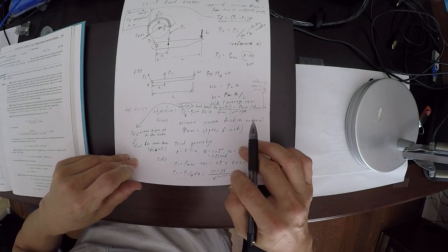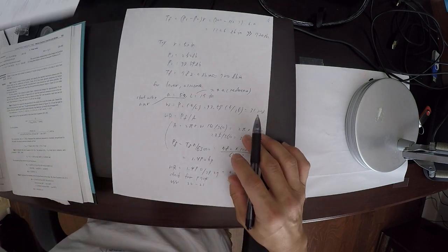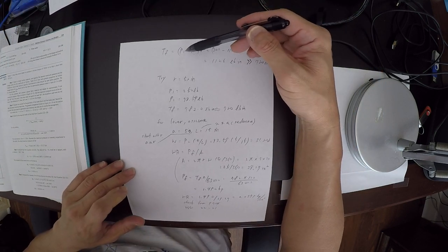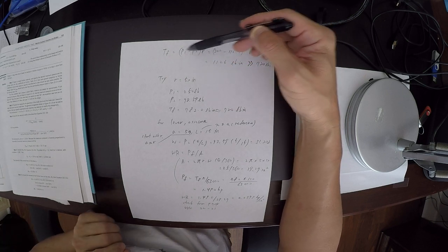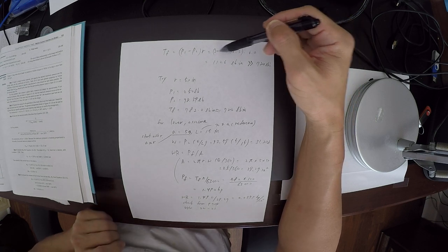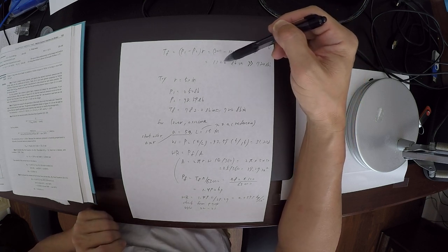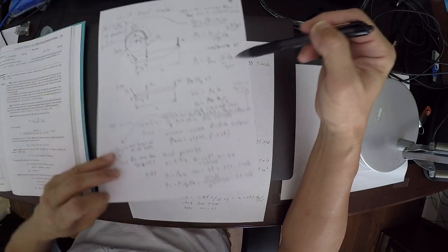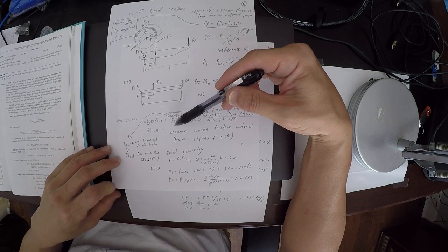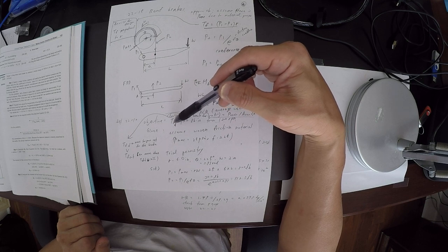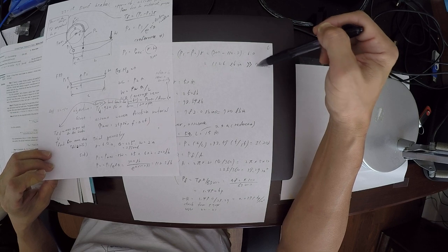With this number, you can calculate the TF from this equation, P1 minus P2 times R, radius. This will give us 1126 pound-inch. But the problem is, if you compare this result with the design torque, it's going to be much more than the 720.